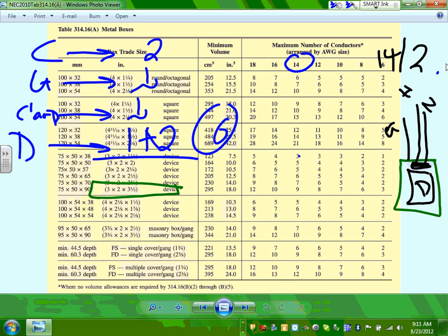Can this box work? The first one. I need 6, remember. Can this one work? Can somebody say no, Chad? No. Can this one work? No. How about this? So what's the shallowest box that I can use? All the way to 3 by 2 by 2.5. Aaron, this is for you. Does it make sense? That's it. That's rocket science about the box fill calculation.